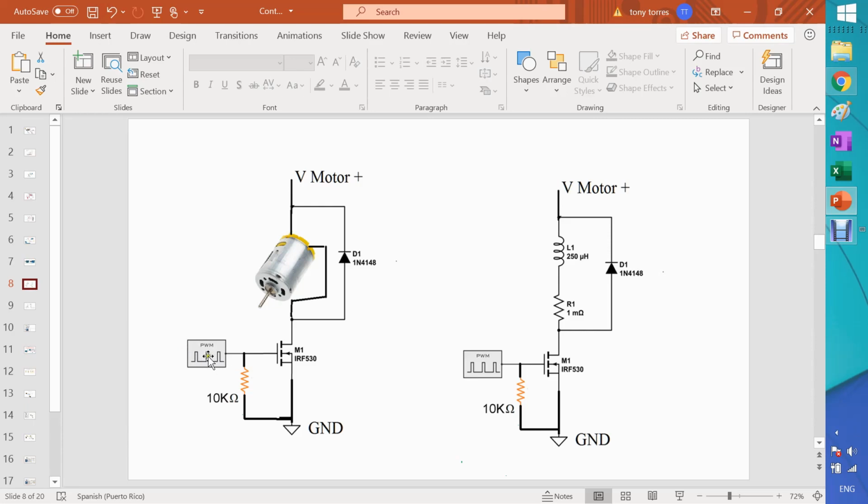So again, analogWrite works, but you have to dedicate the Arduino to do that. You cannot take the Arduino to do something else, because it really messes up the Arduino analogWrite. Now, if I use my scheme, which is to control with any pin the duty cycle of a given cycle time, it worked perfect.